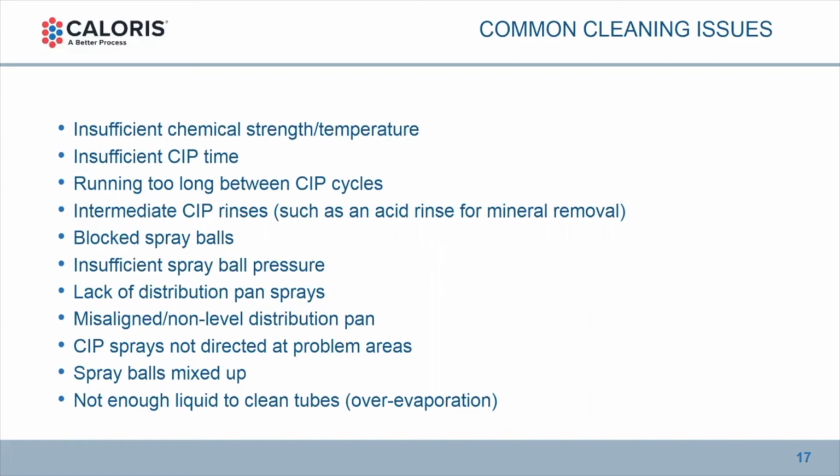And when you look at production efficiency, it's all about maintaining consistent discharge solids from the evaporator system. Because that impacts you downstream, be it a crystallizer or a spray dryer. If you're going straight to the spray dryer, you've got to evaporate more water because your solids dropped for the second half of the day. You're burning energy in the dryer.